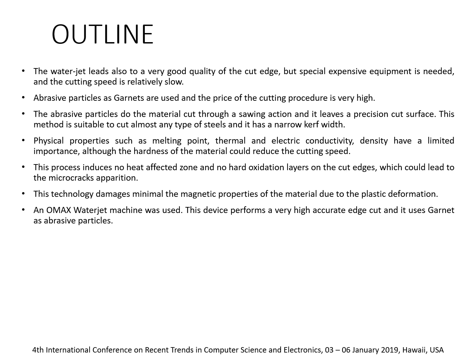This process induces no heat-affected zone and no hard oxidation layers on the cut edges, which could lead to the appearance of microcracks. This technology minimally damages the magnetic properties of the material, due to the plastic deformation. An OMAX water jet machine was used. This device performs a very accurate edge cut and it uses garnet, as I said before, as abrasive particles.